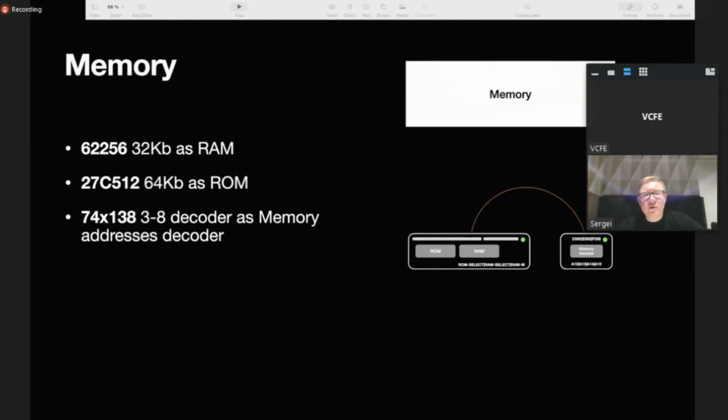If you load it into this ROM, you just wouldn't see the exact addresses, because right now you can edit segment FF00 and it would be exactly the same addresses as the CPU reads them. If we used a 32-kilobyte chip, it would be much harder to program and understand, with this relative addressing.